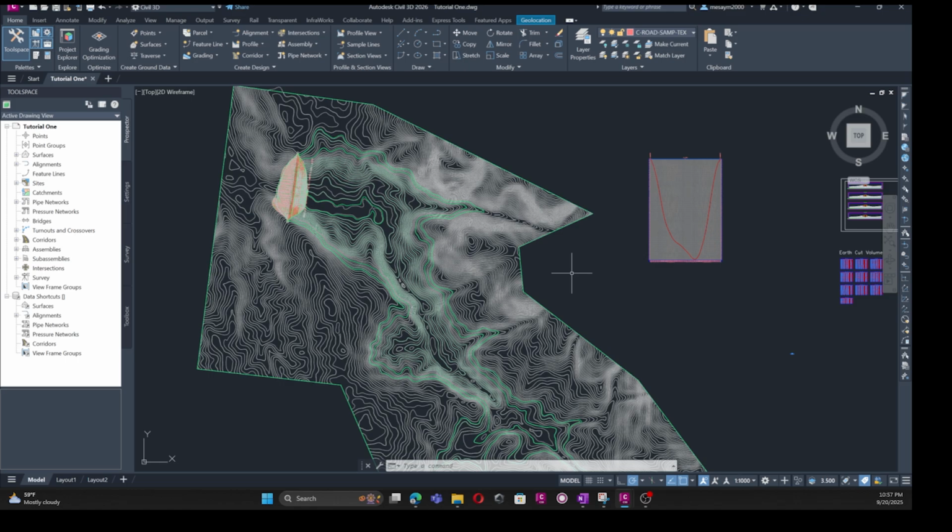The other important point I have to mention is that when we select a dam location, the topography is not the only factor. There are other factors we have to properly consider, like the geology of the area, the strata, the groundwater condition, and maybe any other environmental related factors which should be properly analyzed.